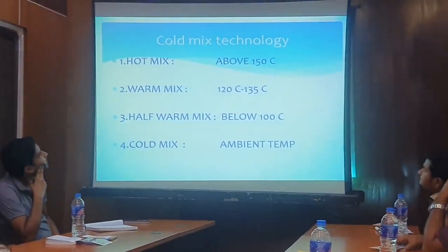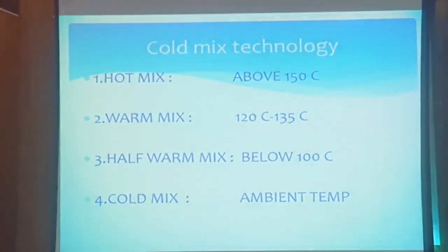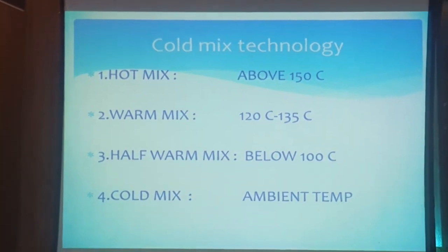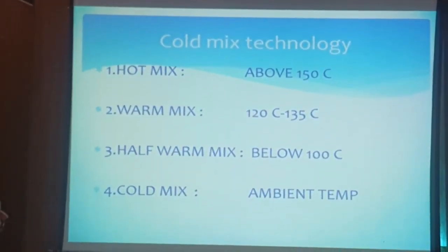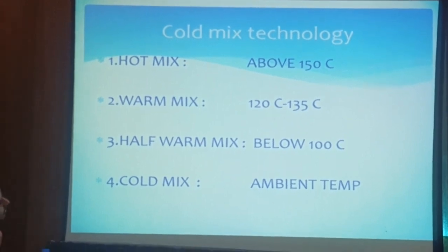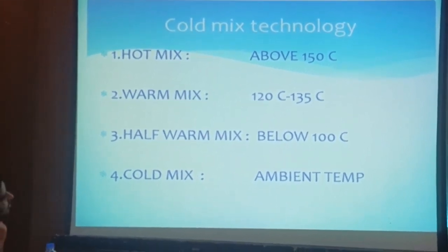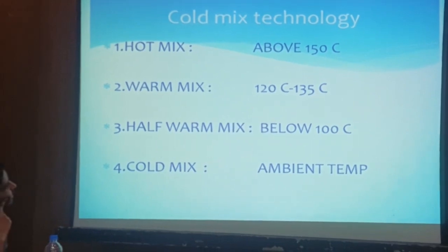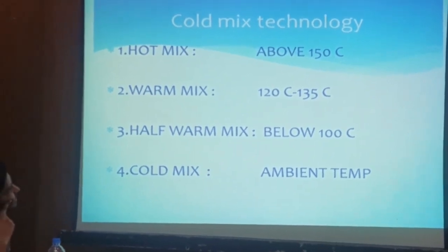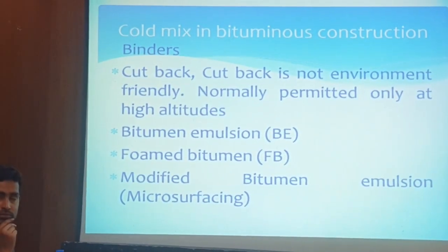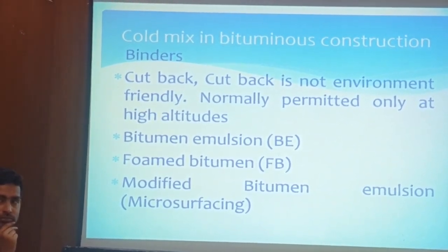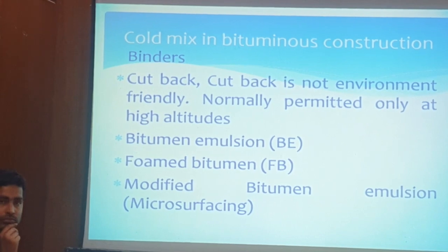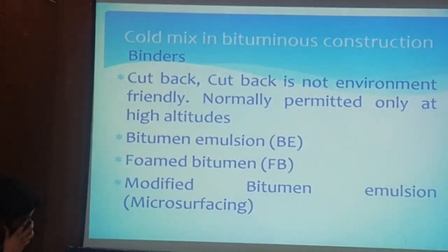Now, the thing you are telling about in PMGSY, the cold mix technology. Hot mix is above 150 degrees Celsius. Warm mix is 120 to 135. Half warm mix, the term I have just used, is below 100 degrees, and cold mix is ambient. What are the cold mix technologies? Cutback bitumen, which I have already told about in the earlier presentation, bitumen emulsion and foam bitumen.